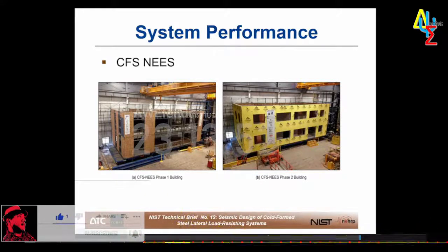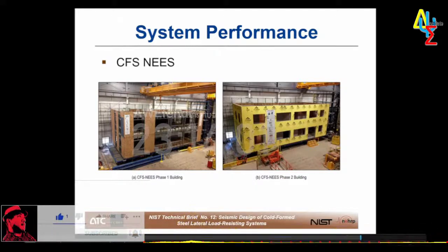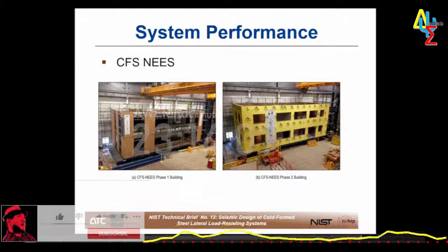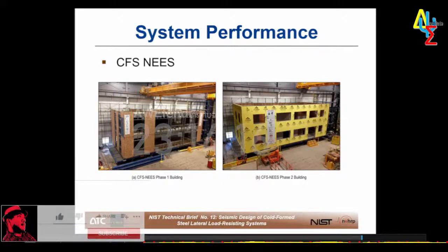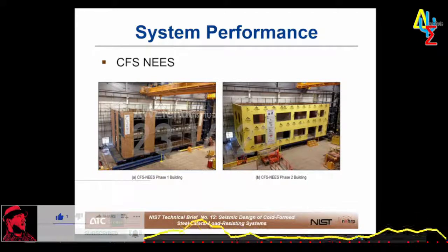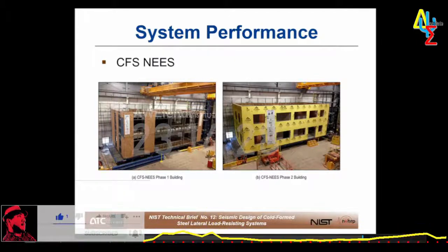Incidentally, that blue structure it is sitting on is a hydraulically actuated seismic shake table. We ran a variety of seismic spectra through those hydraulics to accelerate that structure, mimicking some of the Northridge shaking, I believe it was, and measured all kinds of things about how the system performed. Then we deconstructed that system and rebuilt it, and tested it to make sure it was the same. We ran what were called white noise tests to make sure it was behaving the same as the original phase 1 structure. And then we started adding things to the building and doing additional tests.